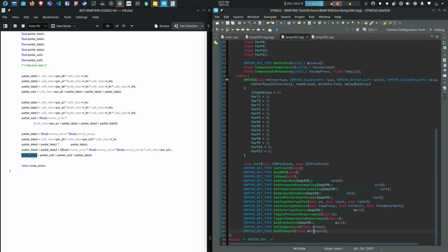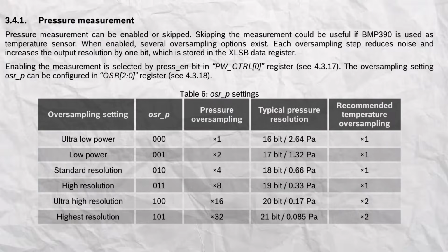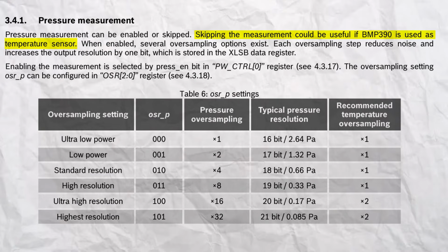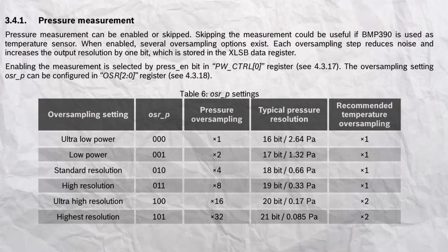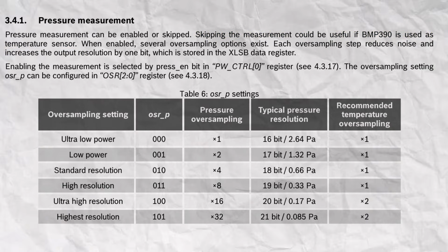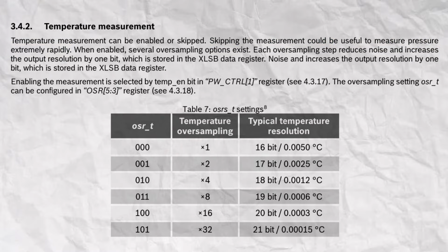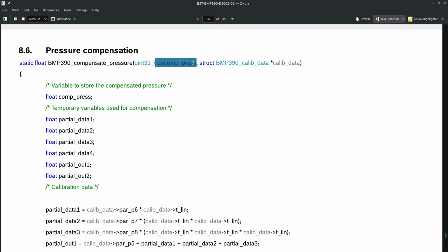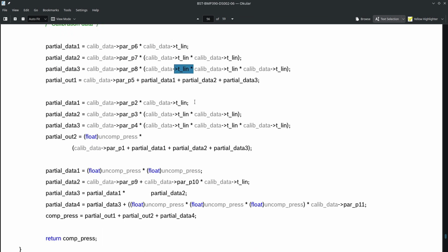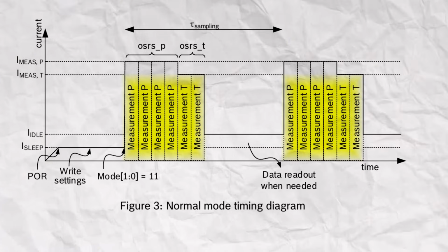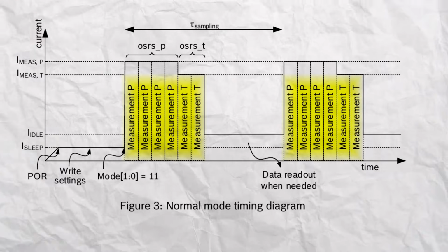The function for pressure measurement differs slightly from the temperature function, as it combines both temperature and pressure measurement into one. This is because the barometer can be operated as a standalone temperature sensor, in which case the getTemperature function is used. While it can be used as a standalone pressure sensor, it is not advised to do so, as the compensation for pressure requires the compensated temperature value. Therefore, both functionalities have been combined into one to avoid reading data from different cycles.